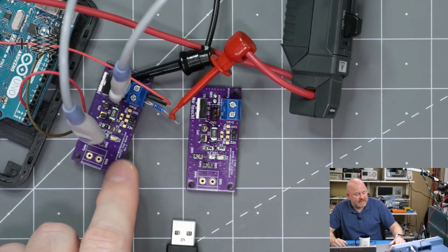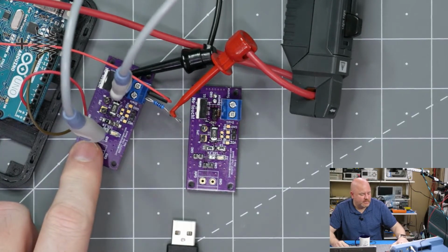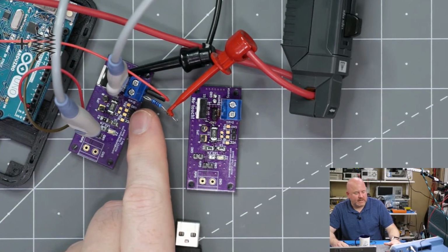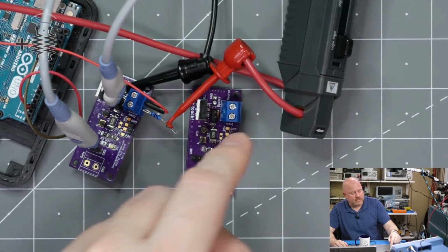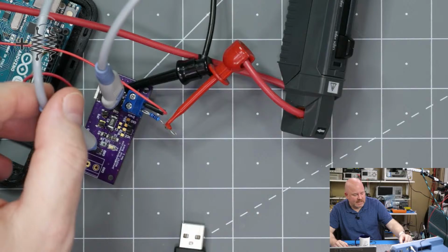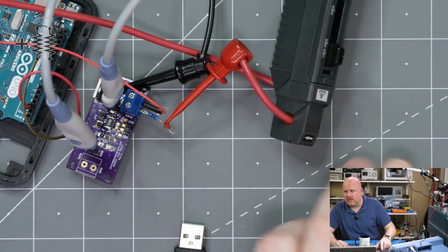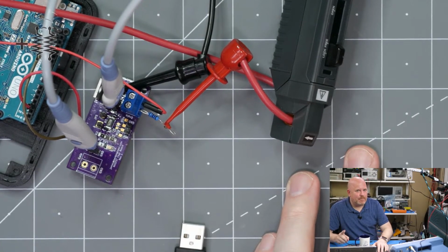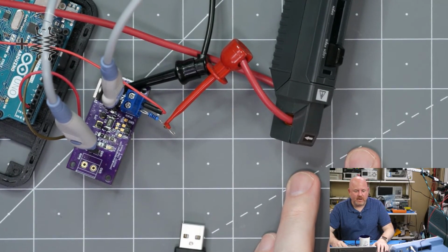In the test fixture we have, the gate is connected to an Arduino Uno, which we're going to reprogram real quick. I just remembered we have to do that. Then I have a scope probe on the gate, a scope probe on the drain and source of the MOSFET, and a current probe clamped around the wire that's providing current into the drain. That way we can see the voltage of the gate, the voltage of the drain, and the current of the MOSFET. I also have a secret probe hooked up to a fourth channel, and I'll get to that. So you'll have to stick around to see what's going on there.